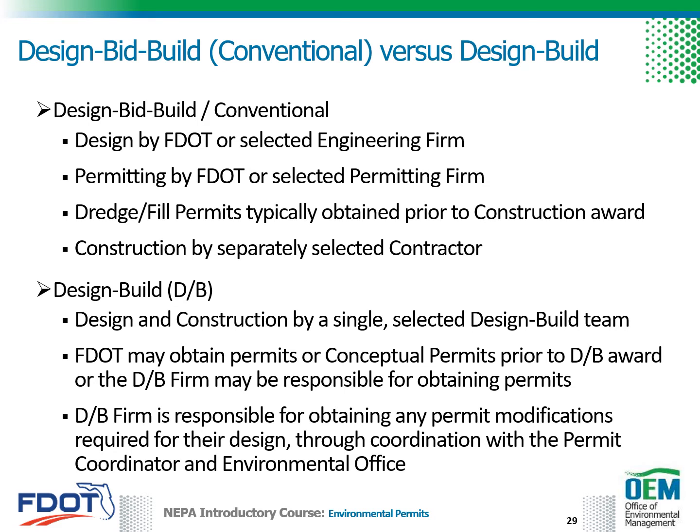A project's contract letting date is the date the FDOT opens bid proposals from potential contractors. Examples of design changes proposed during this process include reducing bridge spans, alternative drainage design, or a change in interchange concepts. During this vetting process, FDOT and the design team must understand which activities the issued permits authorize in relation to stormwater criteria, wetland impacts, and listed species effects, and which design changes would require permit modifications.